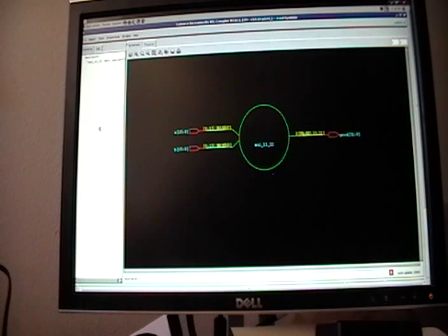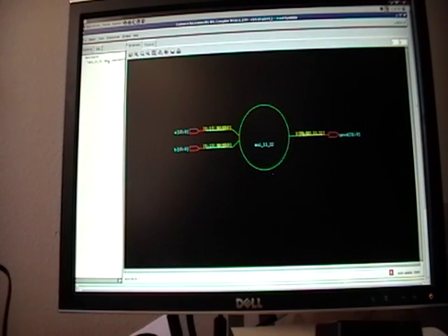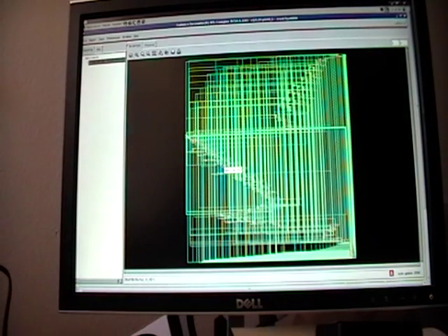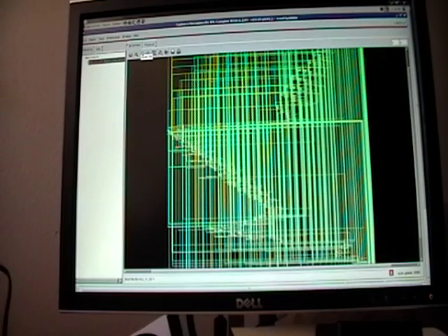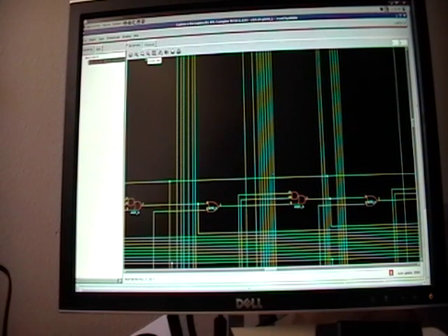And if you work at a company that makes digital circuits, at this point you'll be using a tool like this where you put your code, your VHDL or Verilog, into it, and it turns it into gates. So this is the result of that code that I just showed you. And you can see here AND gates and OR gates and NOR gates.